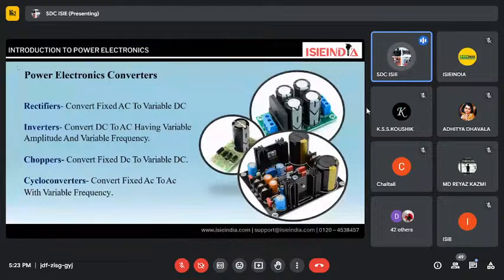In some four-wheelers we are using a permanent magnet synchronous motor, and in some we are using an induction motor. We need DC to AC conversion there, whereas the rectifier converts AC to DC. Basically, while charging an electric vehicle, we convert AC into DC, or we have an onboard charger which has a rectifier circuit in it. I will go deep into the rectifier only, because we are focusing on the electric vehicle.